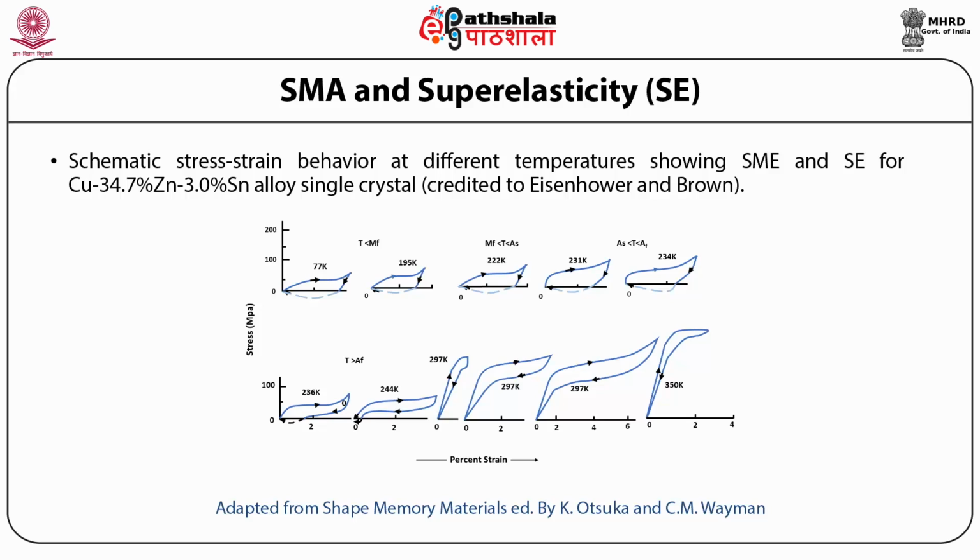What is more interesting is that the elastic behavior is not linear and hence very large strains are also recovered. As stated earlier, this behavior is due to the transition from the parent phase to the martensite phase upon loading, and then the reverse transformation from the martensite phase to the parent phase.